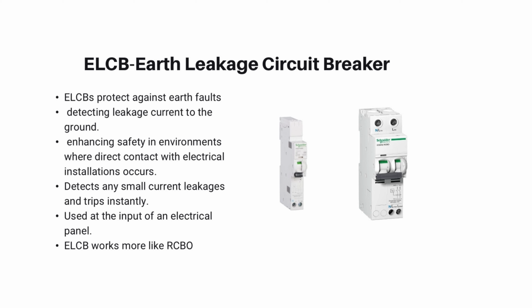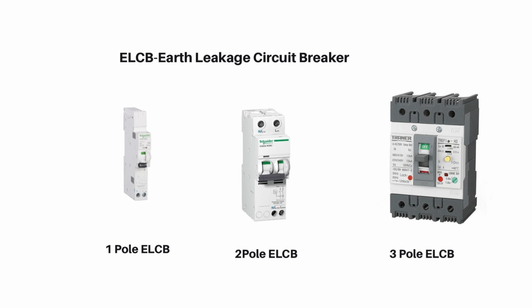They are usually used at the input of an electrical panel, and they are often used in the main distribution panel that will be feeding your control panel, and it is connected in series with the main panel circuit breaker. The earth leakage circuit breakers are connected to the phases, the neutral and the earth, so that they can sense if there is a leakage occurring by comparing the three phases and the return neutral.